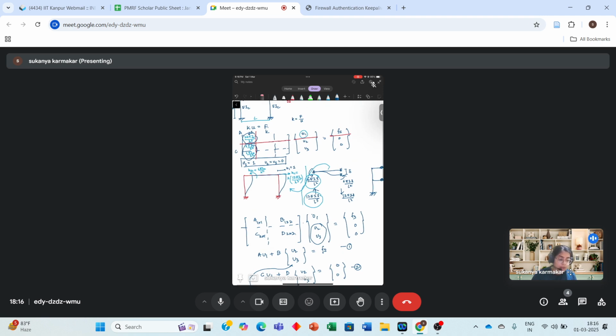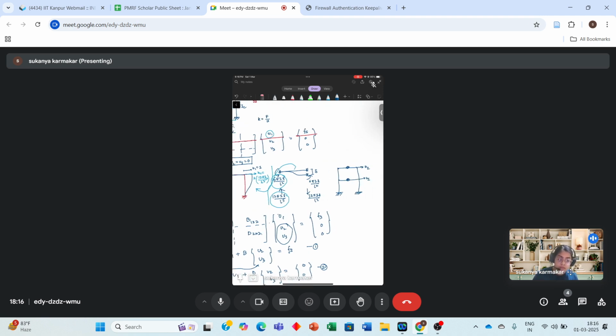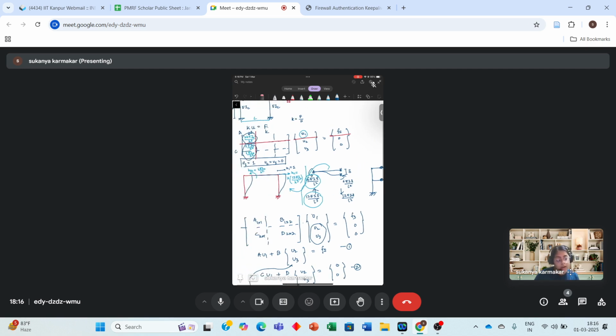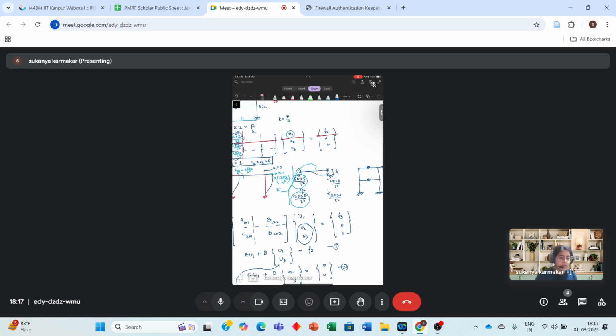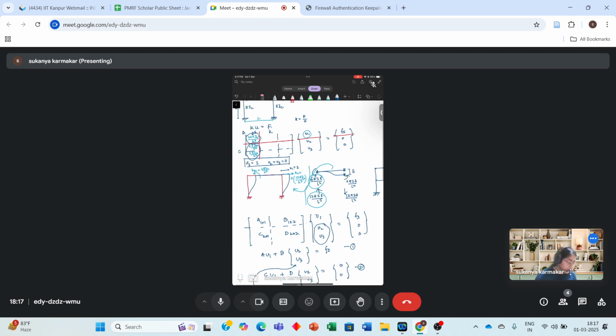So by complex, do you mean a multi-degree of freedom system? Yes, multiple springs, also columns could have axial deformations. Then you need to keep those degrees of freedom. Then you might not use this procedure. Okay. So U2 and U3 are not necessary in this process. If you remove them, it won't affect your solution. That is why I remove them. Got it.